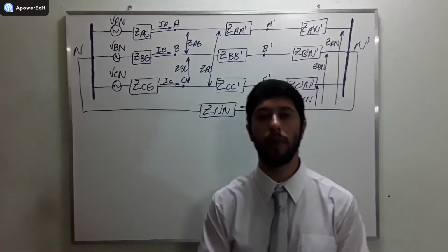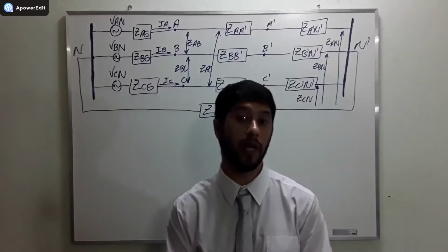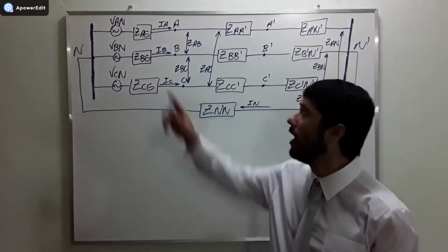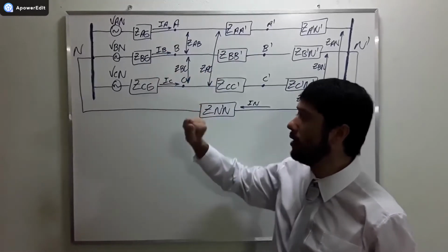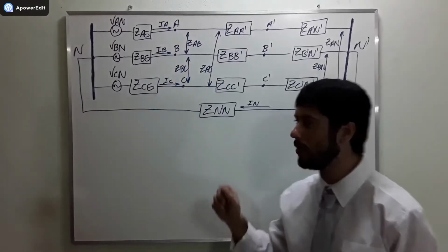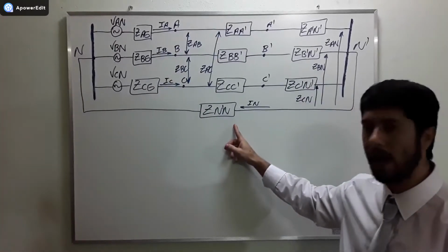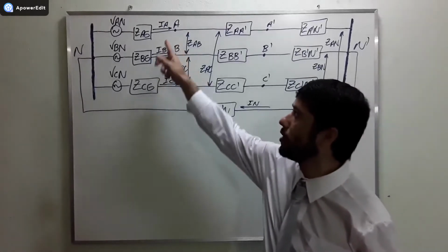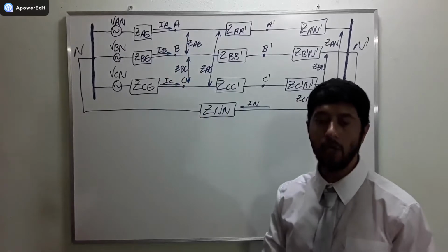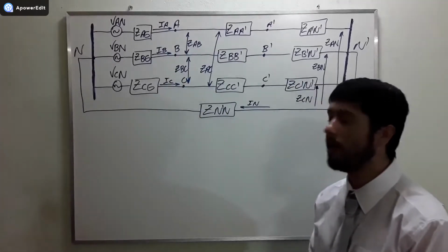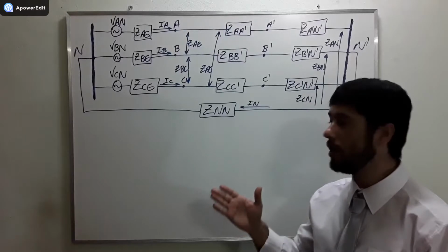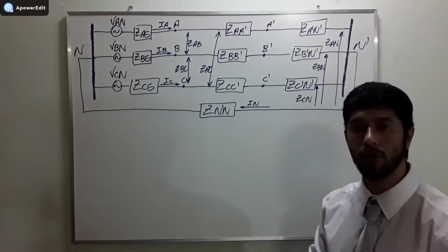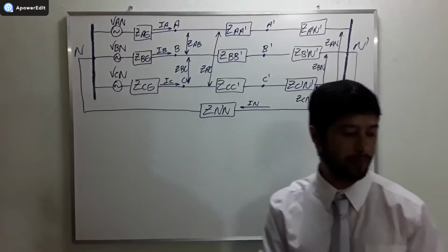In this video I speak about Kron's Reduction applied to electrical power systems. Our objective is to calculate the line currents IA, IB and IC, but when there is a ground system or a neutral wire, the ground system or neutral wire is going to influence the value of the currents IA, IB and IC. So, to properly calculate the value of the line current, we need to discount the influence of the neutral wire or grounding by using Kron's Reduction. Let's understand the problem.